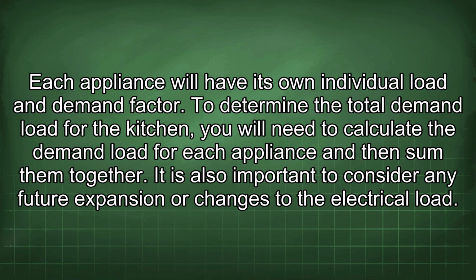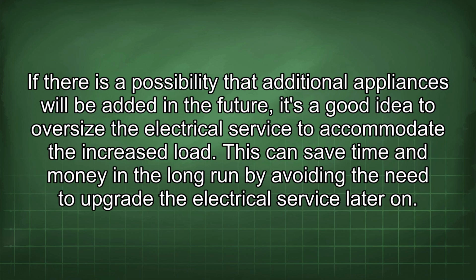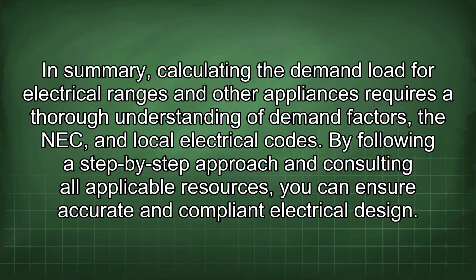It is also important to consider any future expansion or changes to the electrical load. If there is a possibility that additional appliances will be added in the future, it's a good idea to oversize the electrical service to accommodate the increased load. This can save time and money in the long run by avoiding the need to upgrade the electrical service later on. In summary, calculating the demand load for electrical ranges and other appliances requires a thorough understanding of demand factors, the NEC, and local electrical codes. By following a step-by-step approach and consulting all applicable resources, you can ensure accurate and compliant electrical design.